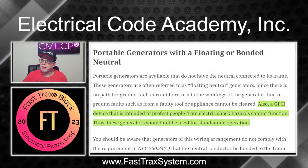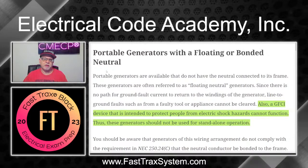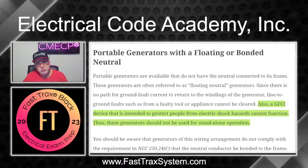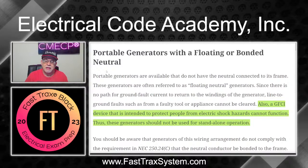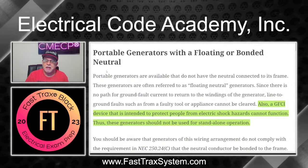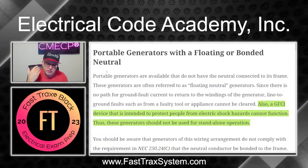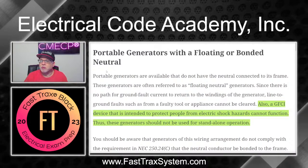Let's dig a little deeper here. And I've got an important area highlighted here for you. Portable generators. Now, there are two different types of portable generators that you're going to run into. You're going to get some that are the bonded neutral, like what we just saw, okay? And then you're going to get a floating neutral. Now, if you think of the bonded neutral, the one we just talked about, then that's going to meet the rules, and that's going to allow the overcurrent devices on the generator to trip. That's going to allow the GFCIs to function properly. Whereas on a floating neutral, that just can't happen.